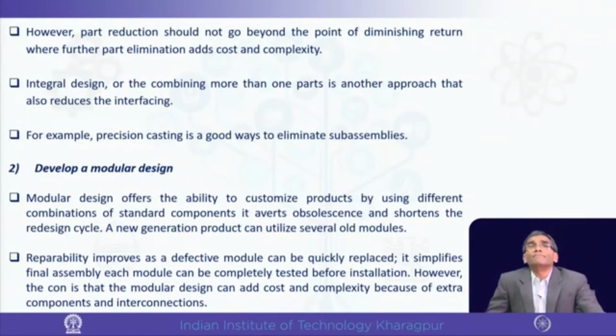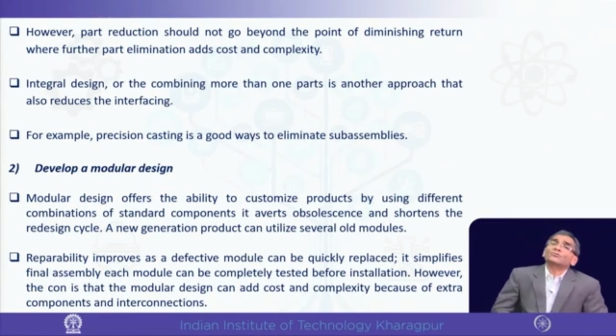However, one thing I would like to tell you is that while part count is to be reduced, there will be some point beyond which, if we try to reduce further, the cost may not actually lessen, it will go up, as it will be a complete integrated heavy part. It is based on integral design, and sometimes there are certain disadvantages, for which we have already discussed modular design versus integral design in the product architecture lecture.